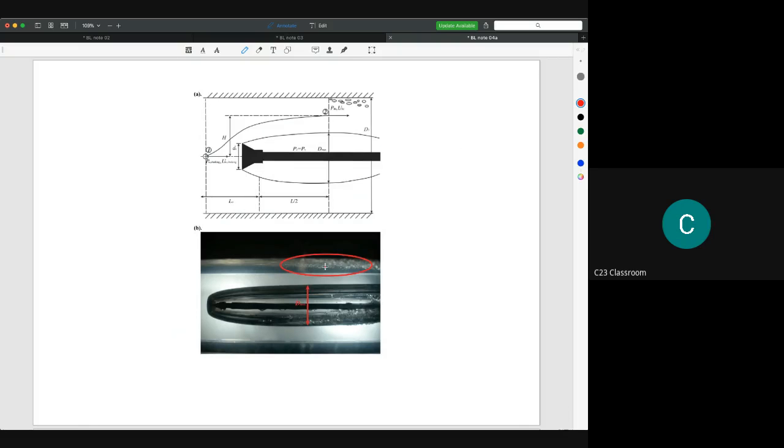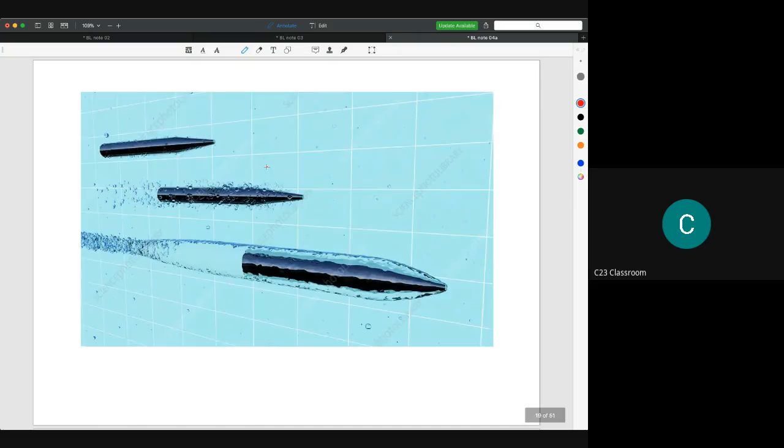So this is the common experiment. For example, we have something like this, and we have flow from left to right, and suddenly we could create a bubble around the object. Maybe the shape of this one is the trigger to have the supercavitation. But sometimes if you have a very fast torpedo, for example, it will create a super lining, actually, because it could reduce the drag force.